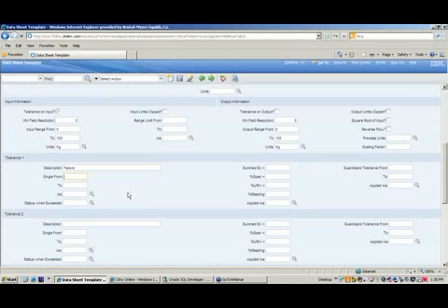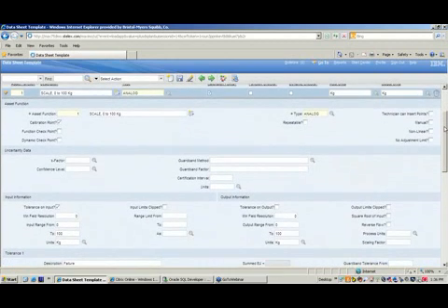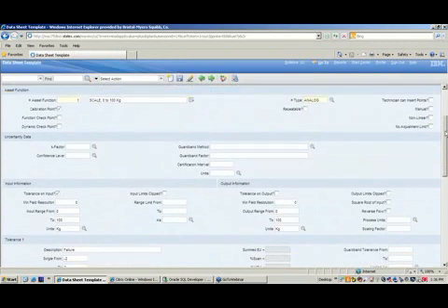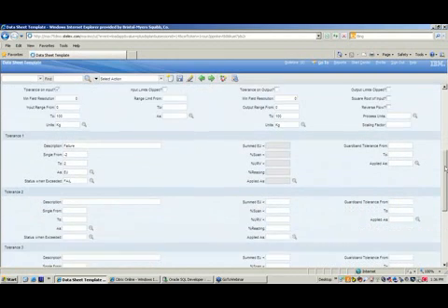And if your tolerance range is basically a percentage or an engineering unit, you define it at this process. We're basically going to look at plus or minus 2, and we'll use engineering units. And the status, if it happens to exceed this, will be to fail. Okay? So from the basic setup, we are looking here at a complete asset function. We set a description, we told its calibration points, we gave it our input and output information, and we gave it a tolerance limit.